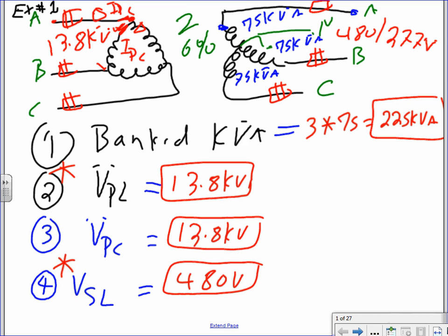Look at this. Here's the coil current coming out of here all the way. It becomes line current. One more time. Coil current, line current. Aren't they the same? In a Y, the coil current and the line current are identical. Current goes and it starts as a coil and becomes a line. In a delta, it's different. It comes here as a line, then it's split here as a coil. Cool? Everybody understand that one?